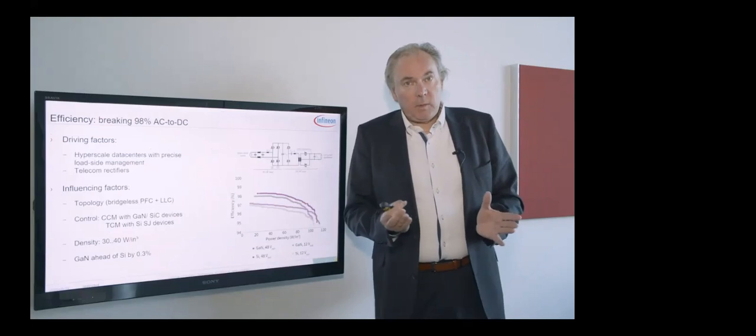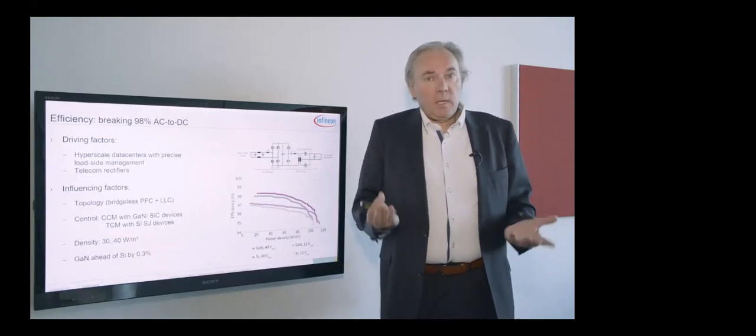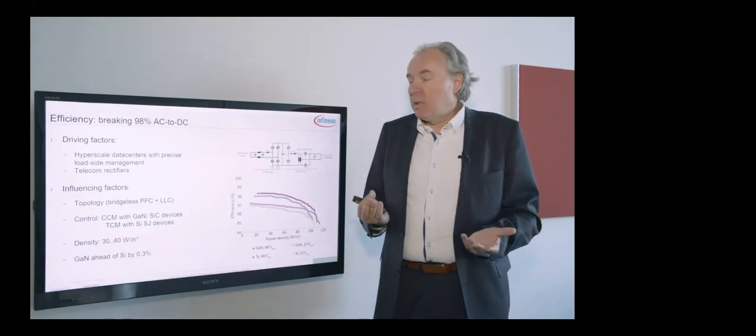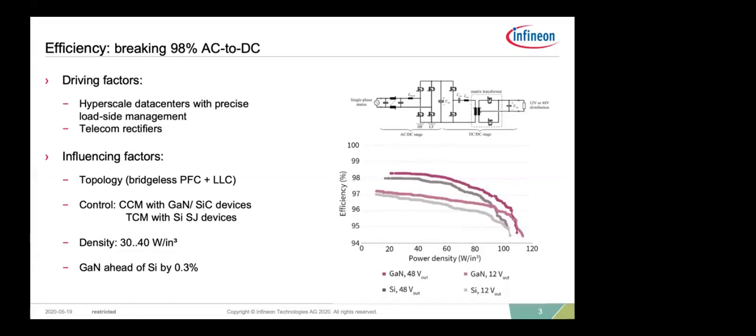When we are optimizing such a topology towards efficiency, typically in 3 kilowatt power supply units and an N+1 redundancy, we need a bridgeless PFC topology. We need to get rid of the bridge rectifier.